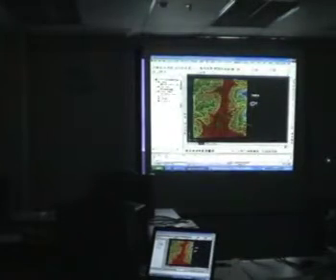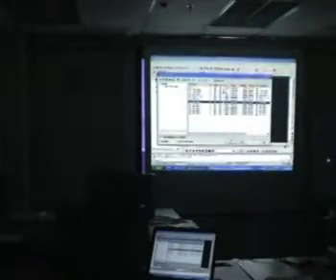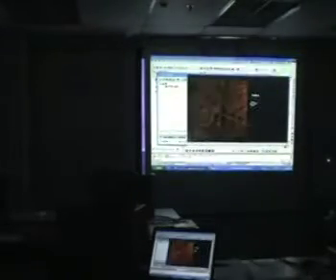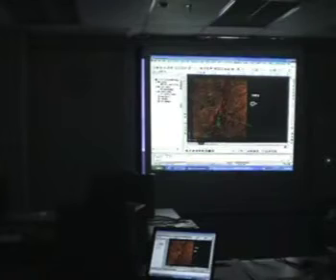Let me show you some of the other major features of Land Desktop before we go to Civil 3D. Because Land Desktop is very powerful for earthwork calculations as well. I'm just going to switch off the layers so that we get left the contour line. So at least we kind of know where we're looking at. I'm going to create a proposed level here, like a platform, so that we can run our volume calculations.